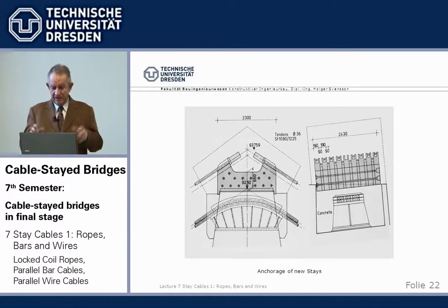So then, at the end, 2 or 3 ropes broke completely. And then people took notice: oh, something is happening. The wire breaks were of no interest there, but then we were asked, and we finally said, okay, we'll replace the old ones with new ones. We had a new saddle installed on top, installed new ropes, and took out the old ones.